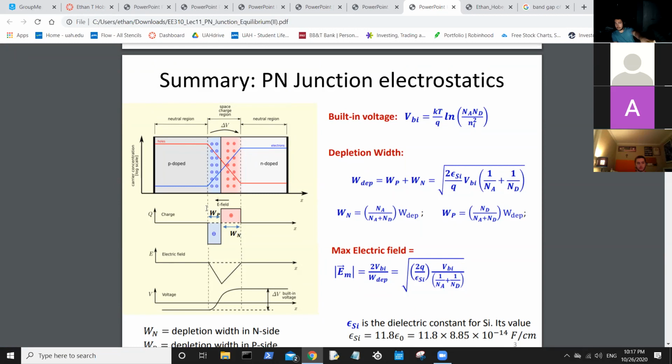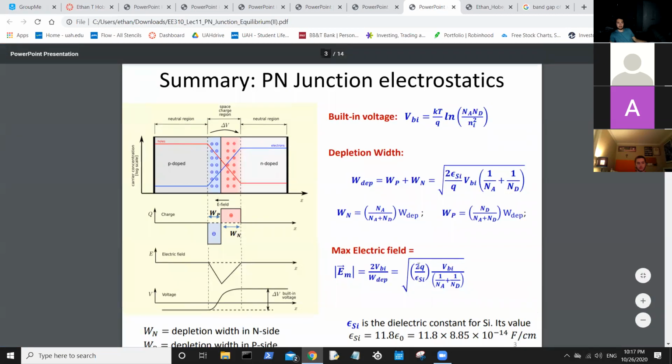So this figure is the exact inverse of the question. If we were to invert it, then you would obviously see that where those carrier densities are equal, when they cross each other on the N side here, you flip it and that's the P side. You can see that the maximum resistivity point is in fact on the P side. So that's just a graphical way to represent that.